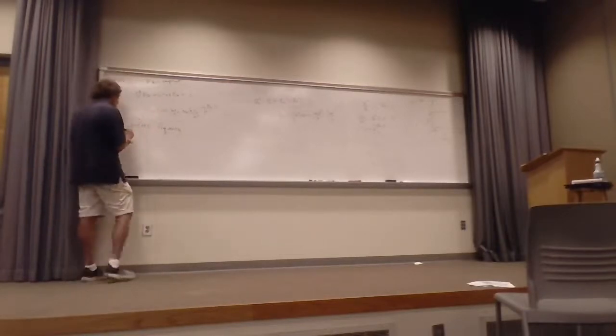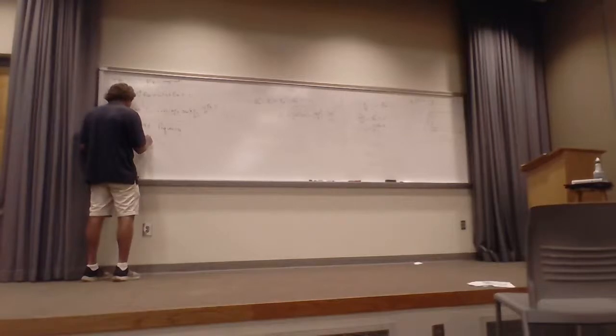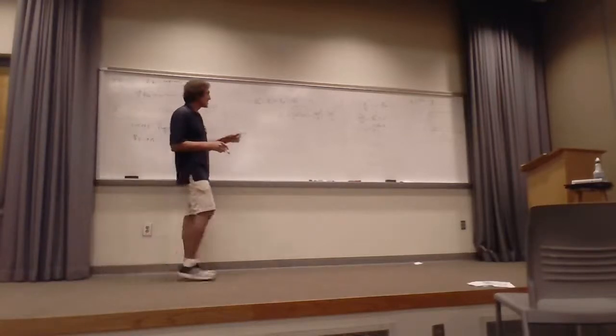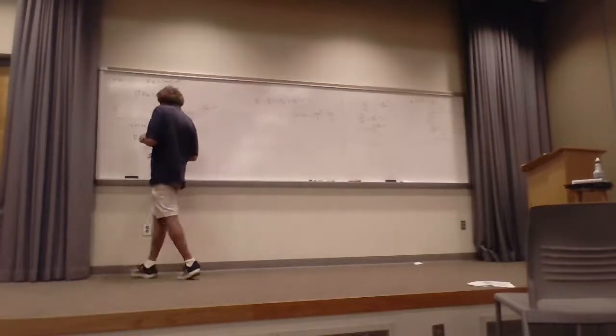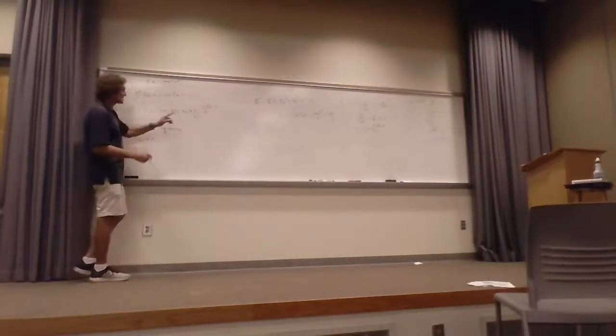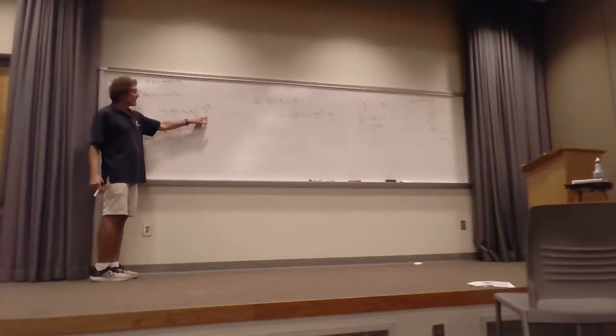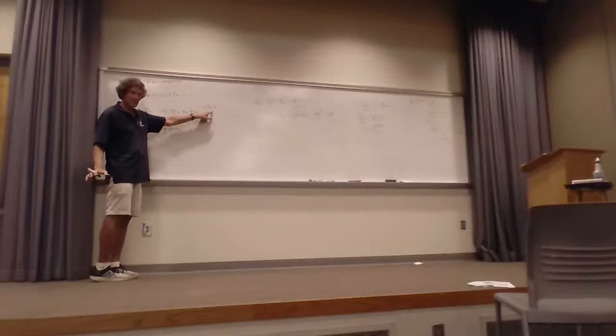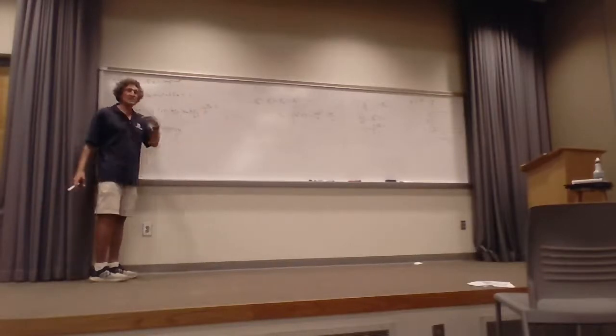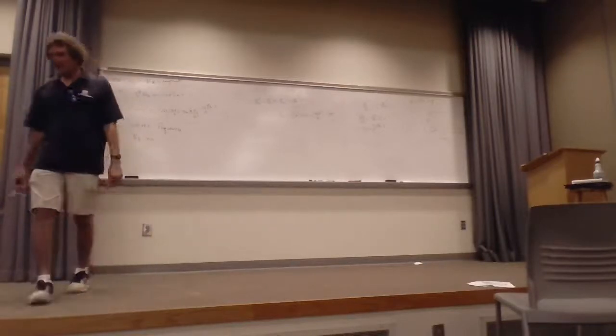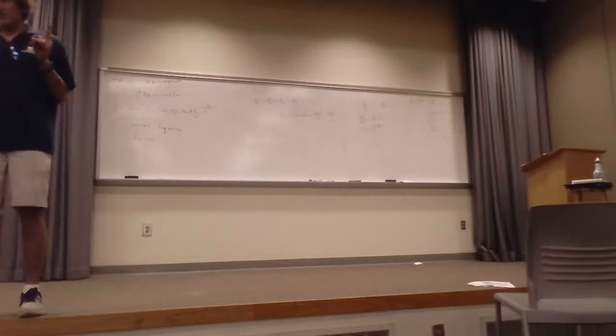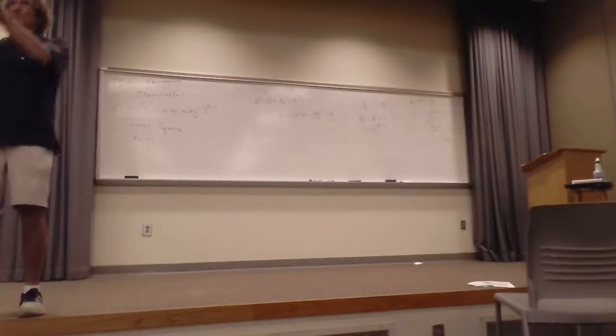All right, we let beta z go to 0. Now, when I say beta z, what did that have to do with? Think about the solution. See this e to the minus j beta z times z? If beta z goes to 0, there is no variation in z. Nothing is propagating. And remember, beta is really radians per meter. If your wave changes 0 radians per meter, basically the wave is bouncing up and down.